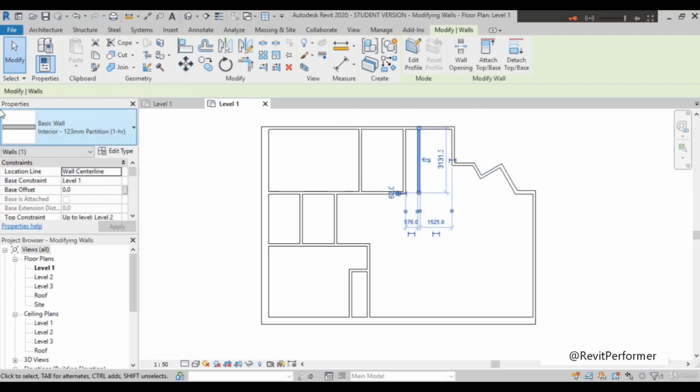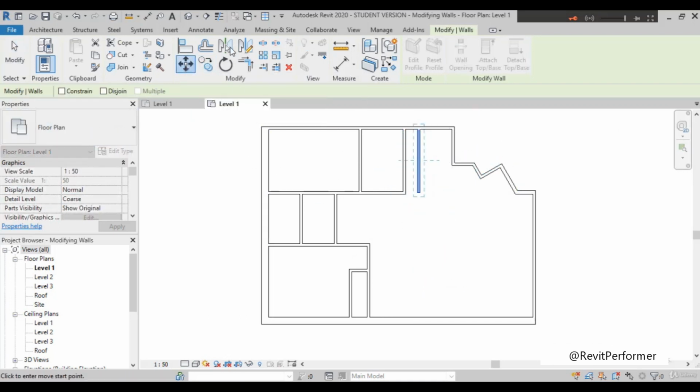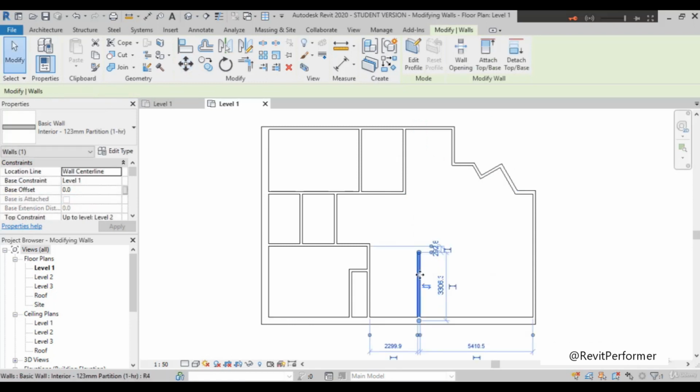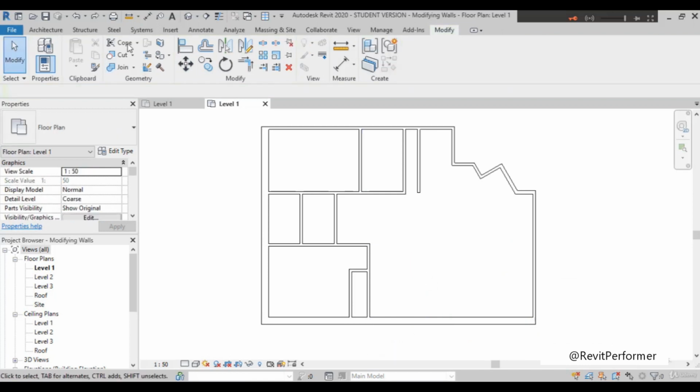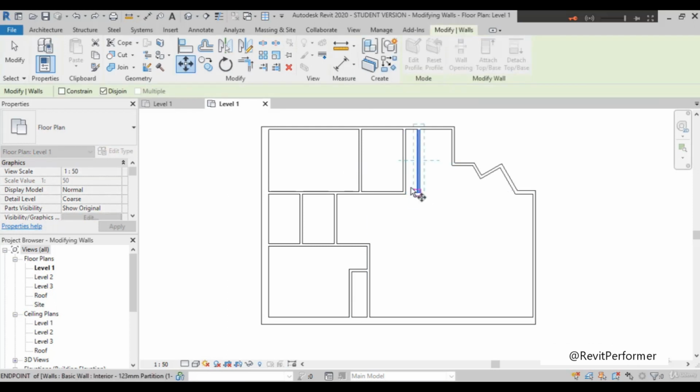One thing that is very important right now: when you go to the move command, if this join check is on, when you move this, you can see I move it here, so it will move properly. Okay, Control Z, and then when you move it and select the object, then move it like this, and then you can uncheck this box.